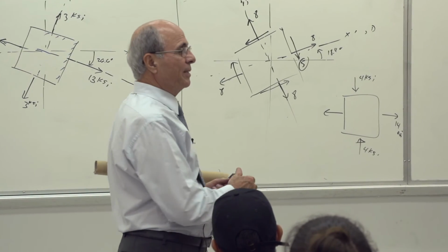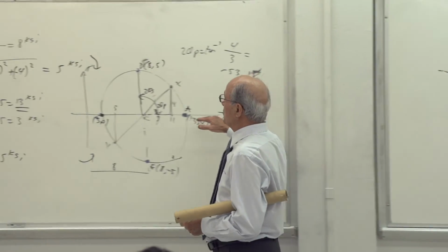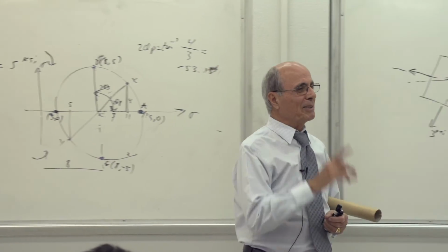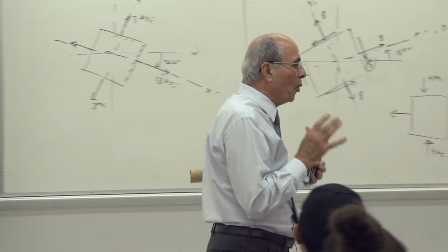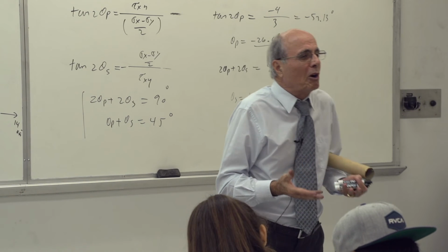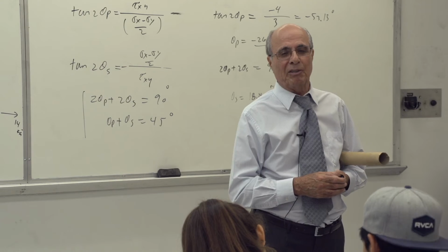Is there a shear there? No. If there is no shear there, aren't you already here? Remember that, write it down. That's the whole clue here. If there is no shear, you are already having a principal stress scenario, yes or no?